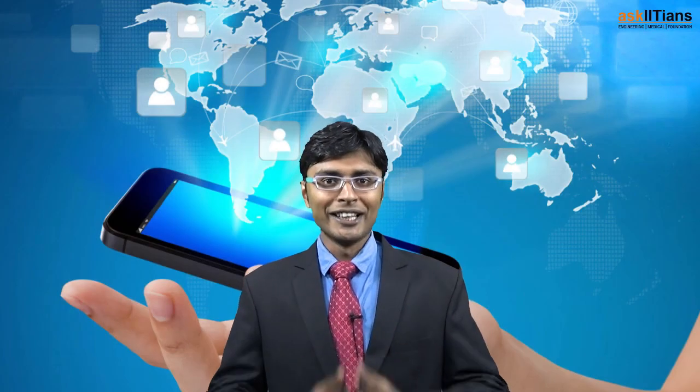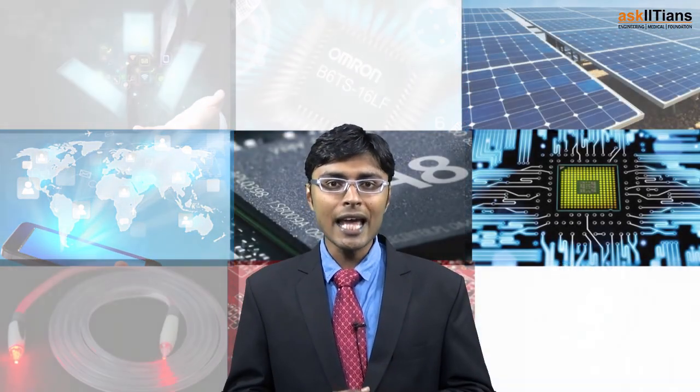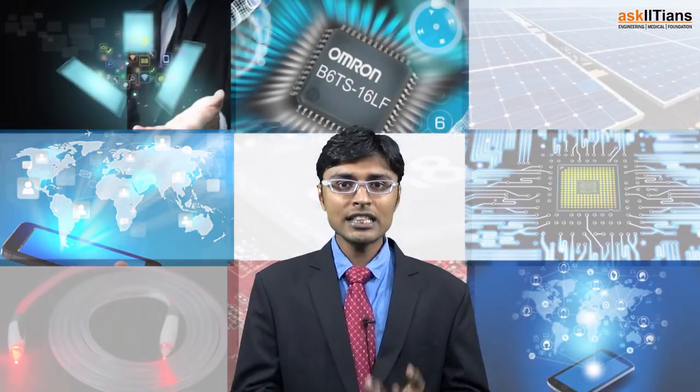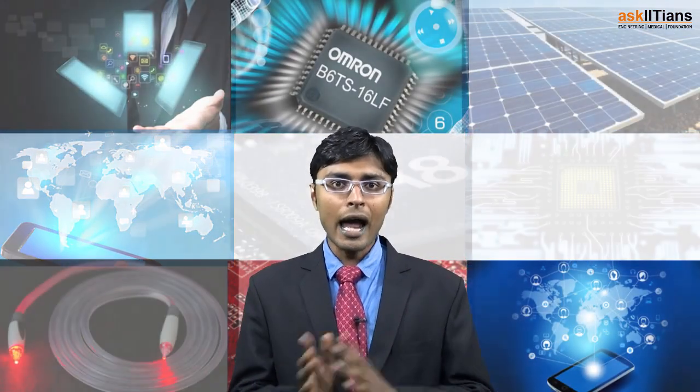So students, in this part we have discussed semiconductors. Semiconductors are the materials whose conductivity lies between metals and insulators. We have also seen that semiconductors have a negative temperature coefficient, which means that with an increase in temperature, the resistivity of the semiconductor decreases. We have also seen the energy band diagrams of semiconductors, metals and insulators, and the difference between all three.